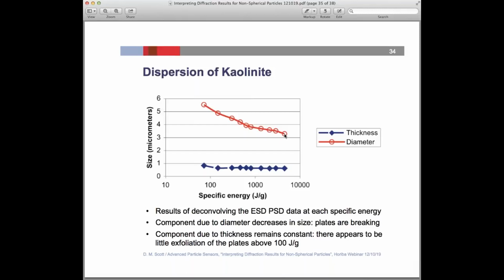So what does that mean? It means that these plates of kaolinite are breaking, but they're not exfoliating. In other words, the plates are stuck together like a stack of cards, and the cards are not coming apart, but the cards are being chopped in half by the rotor stator. So that's a nice quantitative result that we can